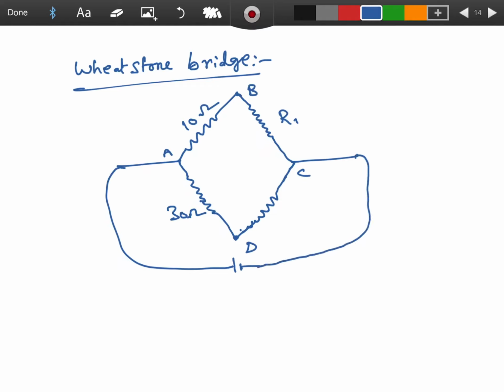In the question I mentioned, in the Wheatstone bridge shown above, what would be the value of R1 and R2 in order to balance the bridge? See, to balance the bridge, this is the situation, like here somewhat galvanometer, here current in this should be 0. But here they didn't give the galvanometer, something else they mentioned instead of galvanometer.